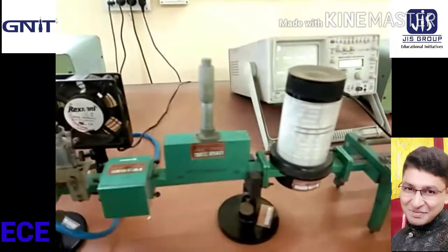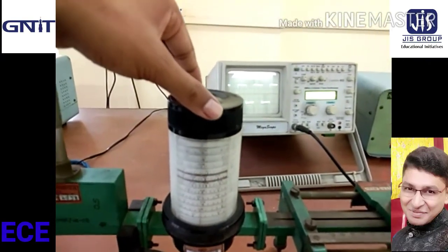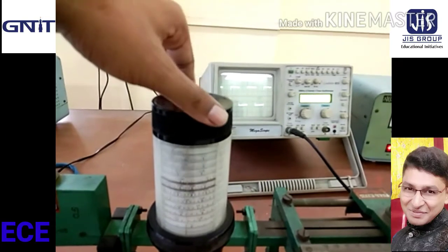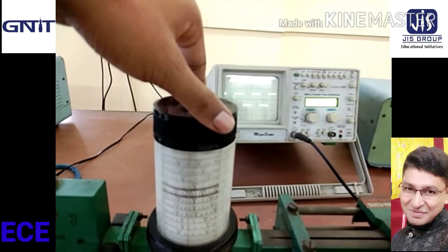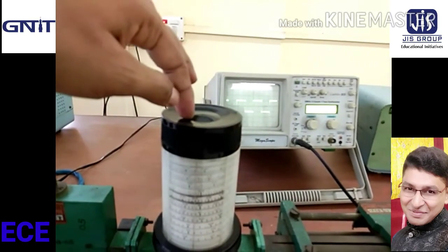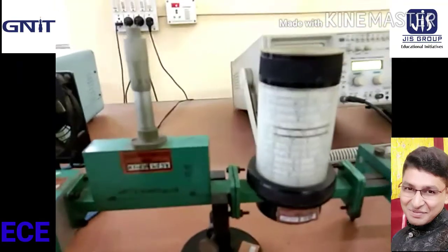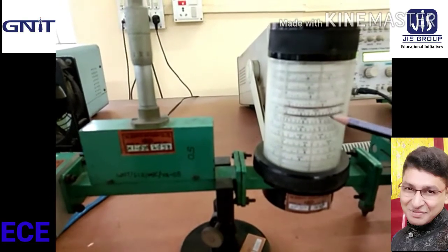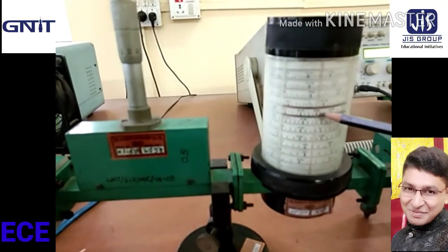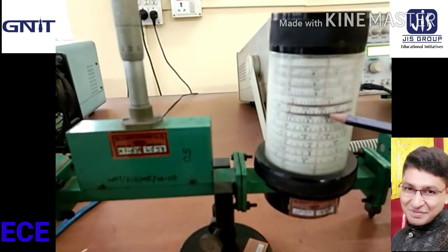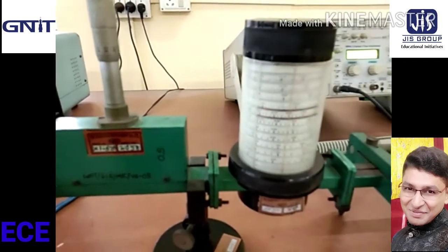Then for the frequency, rotate the frequency meter. When the output signal dips, stop rotating. Where the 2 copper foils are and 1 red line meet at this point, this is your resonant frequency, that is 9.74 gigahertz.